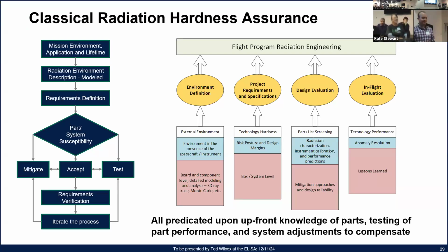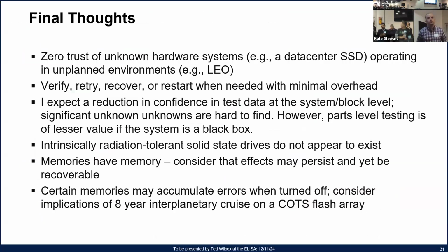I come from the automotive and my previous experience in the industrial domain. What happens in this domain is that the hardware vendor qualifies hardware for automotive or industrial usage. So we do the failure mode analysis of hardware, the number of failures like this one, and we define safety mechanisms in hardware that must be used in order to avoid or detect such failures.